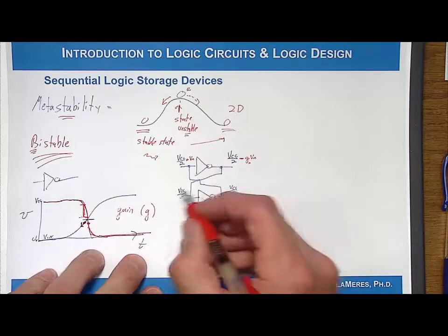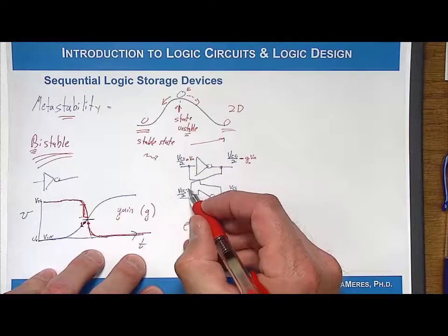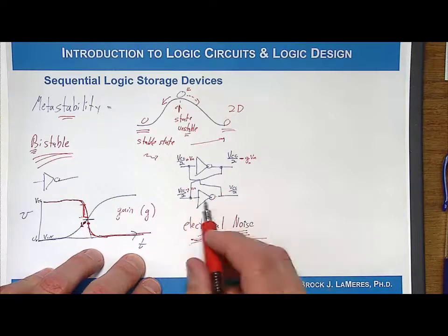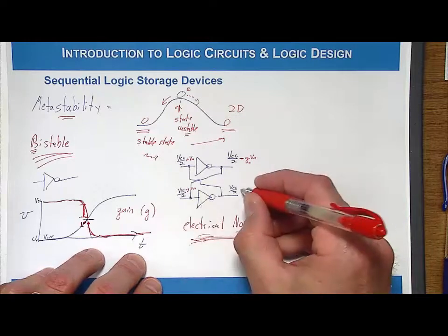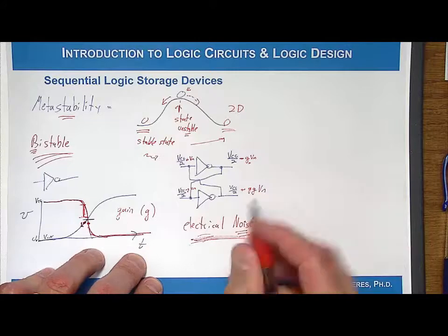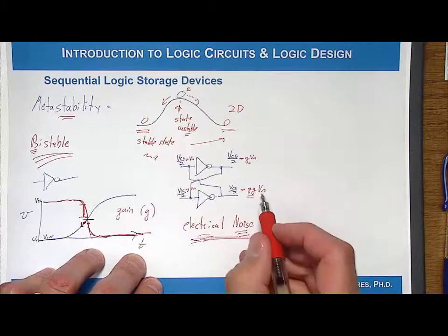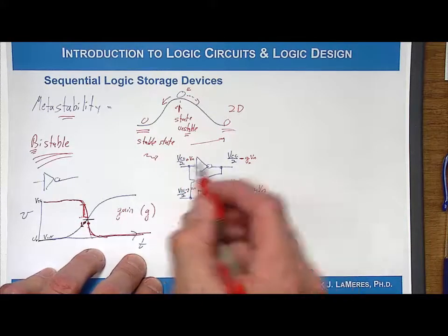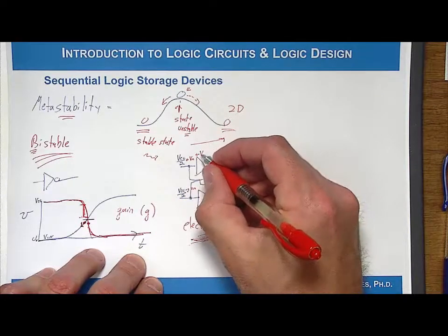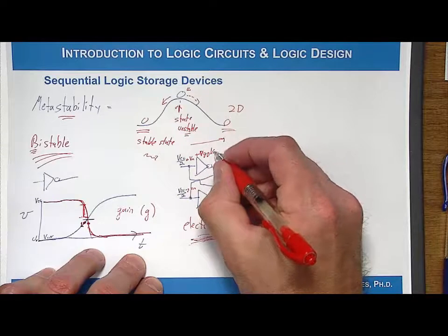Okay, well then that comes back to here and is fed to negative G Vn. Then what happens when you go through here? Well, now you have an inverter which flips the polarity, but you're going to have G times G Vn. So you actually have more noise. Now that more noise is then fed back to here, so now you have plus Vn, but you actually have also plus GGVn, and this thing continues.